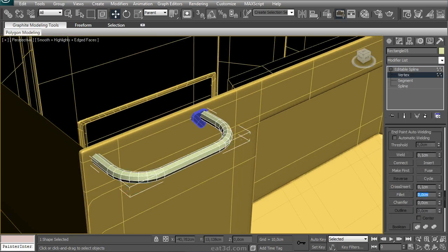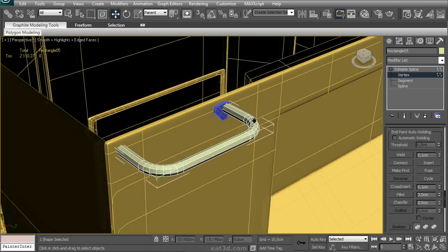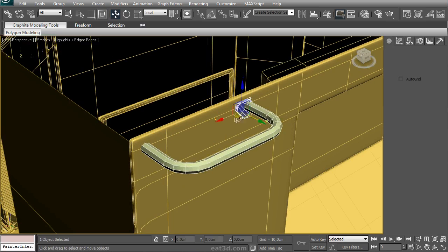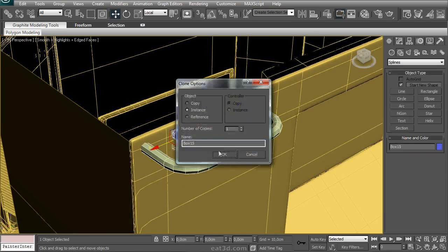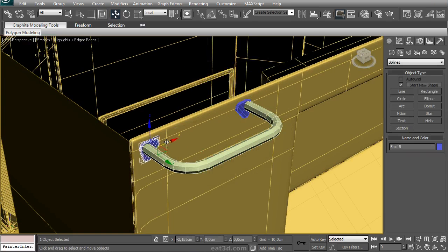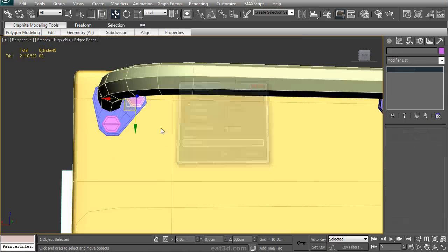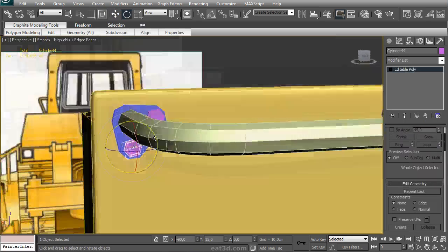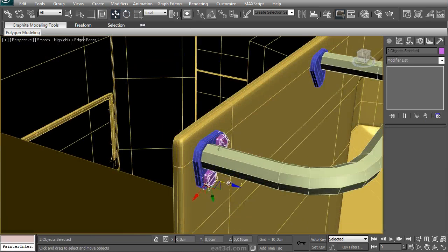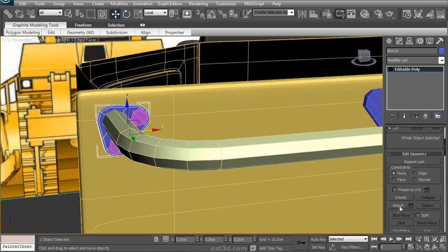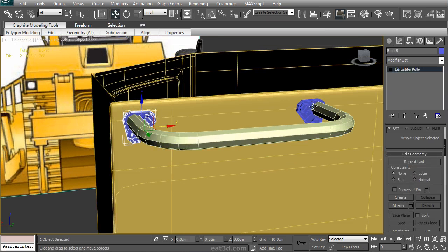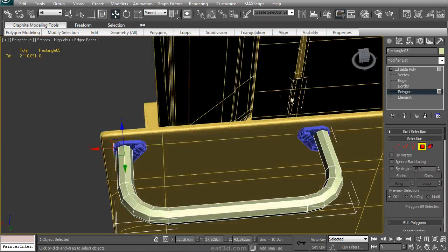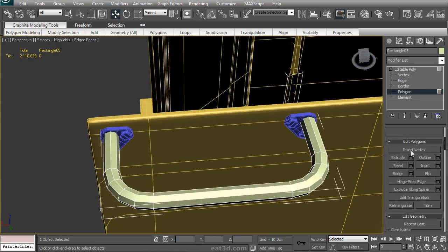Using fillet on the corners. Fillet is such a nice tool in these splines. You can see me use this all through the project. I'm taking the same one as a separate object, mirroring it, moving it into the correct position, then taking these nuts, positioning them, slightly rotating them, and an important detail is the other triangular part is an instance, so the bolts, if I attach them to one, are immediately also attached to the other one since it's an instance.